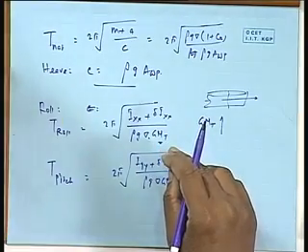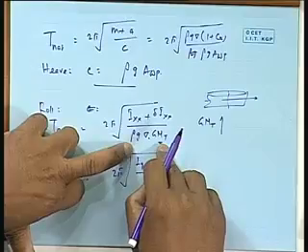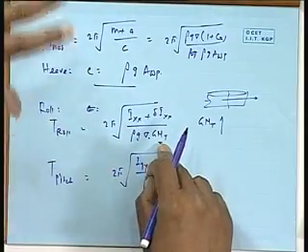It has been found that people are comfortable if this period is about 15 to 20 seconds, or maybe 15 to 16 seconds. But to do that, you actually have to have a lower GMT. Now, there is a contradiction. A passenger vessel, passengers will not ride your ship unless they are comfortable. Therefore, they want a good T natural, 15, 16, 18 seconds. But it is a passenger ship, so you have a higher requirement for GMT, because it should be more safe. So there is a contradiction that a designer has to figure out.